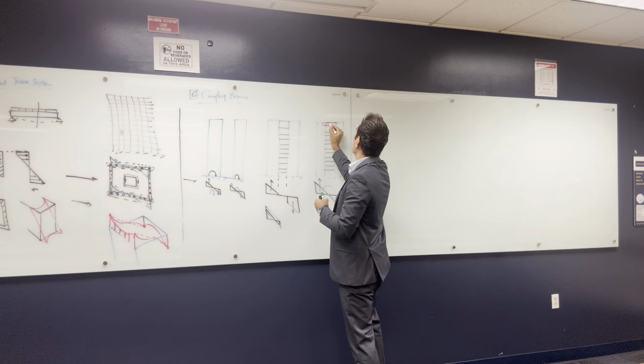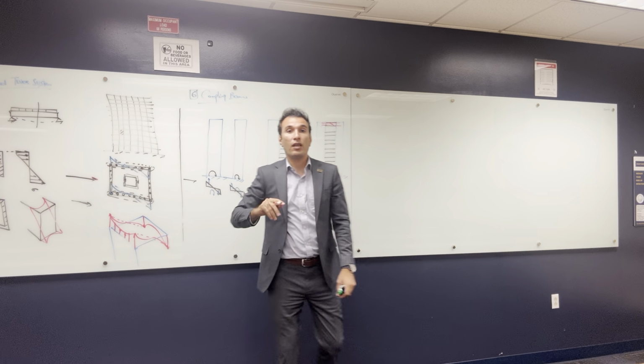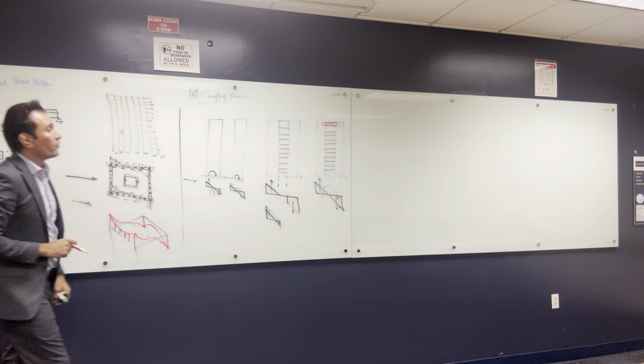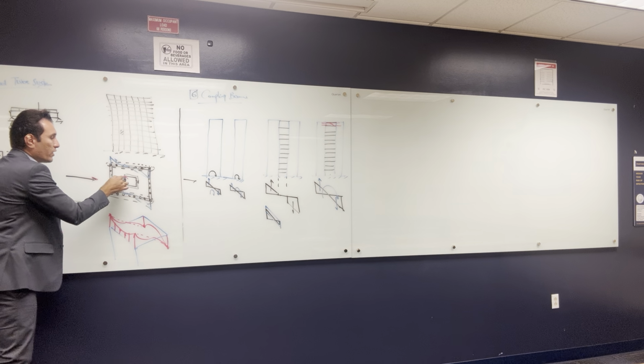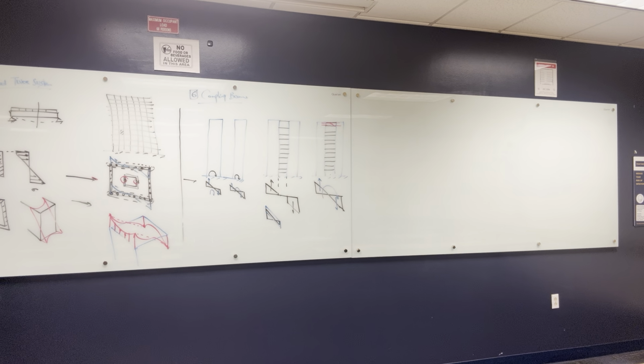And that's not only one bar, that's like a bunch of bars, maybe 5 or 6, depends on how much bending moment this shear wall is gonna have. All right, that's for the coupling beam. So that's what I can do here to complete the tube action, okay?